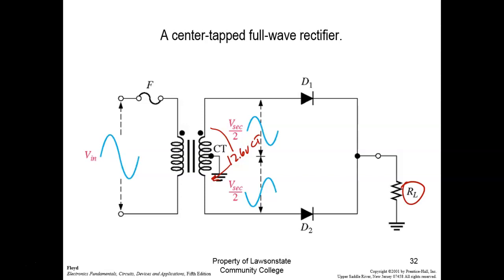You forgot all about that V peak, 2 V peak over pi. You're trying to go directly, trying to give me this instead of what this DC would measure. 4 volts? How'd you get that? So we're just forgetting everything we learned. We're jumping directly from RMS over to VP without going to VP. That 12.6 volts is RMS. My formula says it doesn't say RMS. It says my volts DC is going to be equal to 2 V peak out, not RMS, over pi. So y'all are trying to go from RMS directly to the output without finding what V peak is going to be.